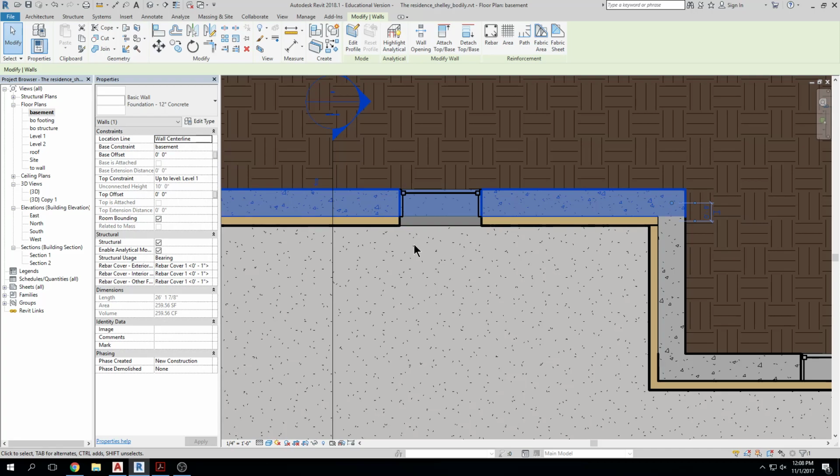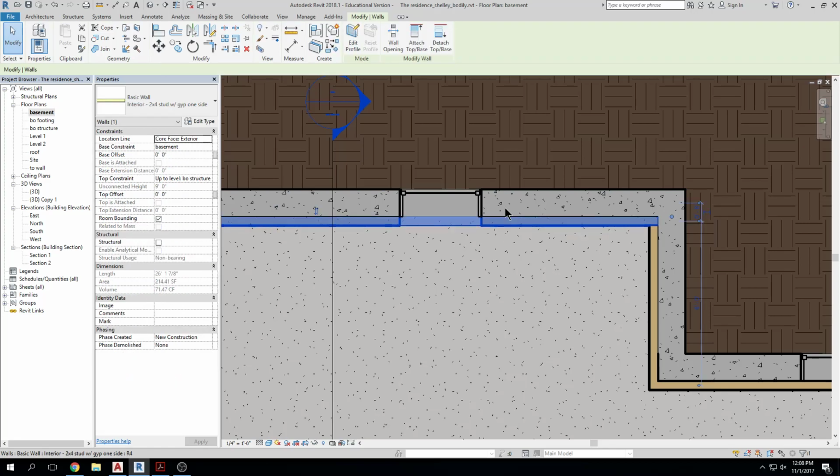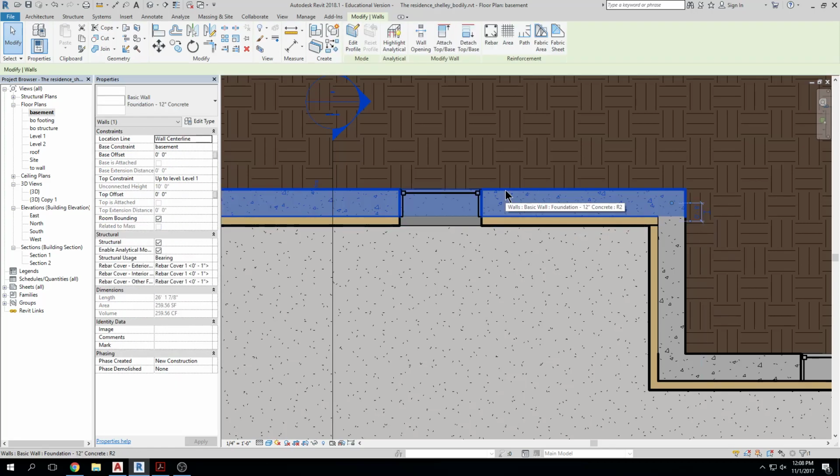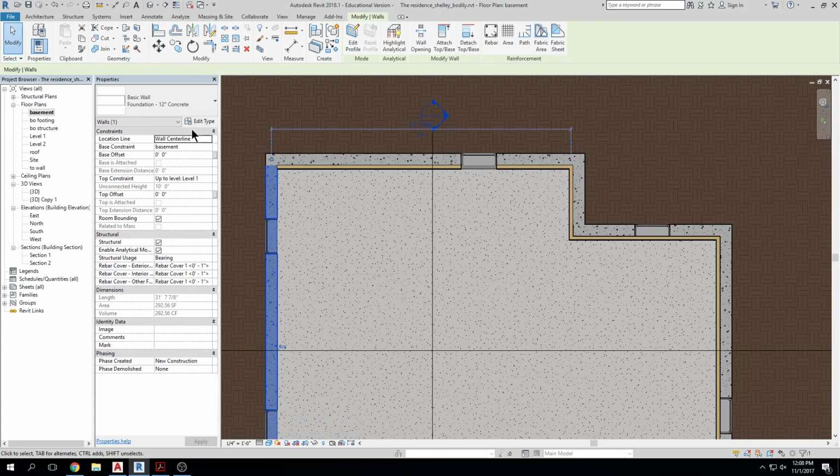I don't typically go this direction, but you can, right? Maybe if you had to create a wall that was lower. This would be a good way if you wanted to only have a 3-foot wall or something for whatever reason in a basement on a foundation wall, maybe there's an access panel or something. Okay, this would be a good way of going about it because I can take this wall and define it with a different height than that wall. Okay, there's an advantage. Normally, what I will do is I will finish face exterior, so my, ooh, that wall's flipped.